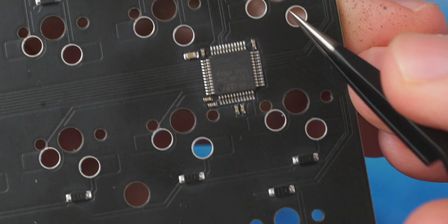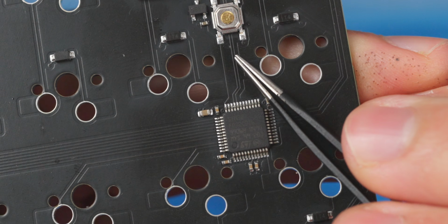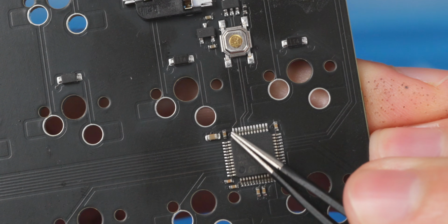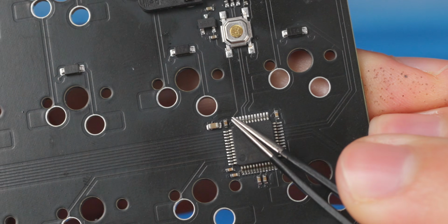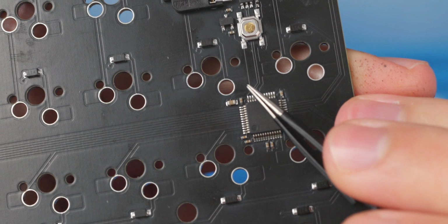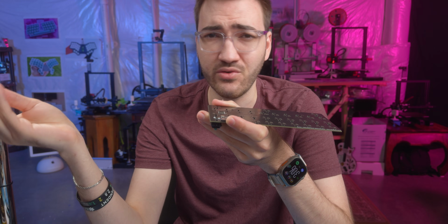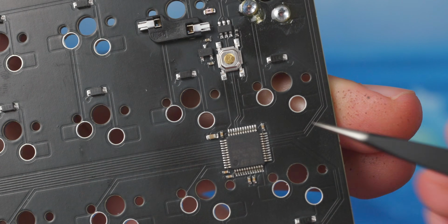Now if we look down below, we can see our traces feeding down. These are of course our data lines in the middle here. This one will be our 3v3 voltage feeding into the pin right here. On this one, I did feed it into the pin. Like I said, it doesn't really matter where you feed that because they're all so close here. As you can see, it doesn't matter if you feed it into the capacitor or the pin. Maybe technically there is a right reason to that, but this works from testing.